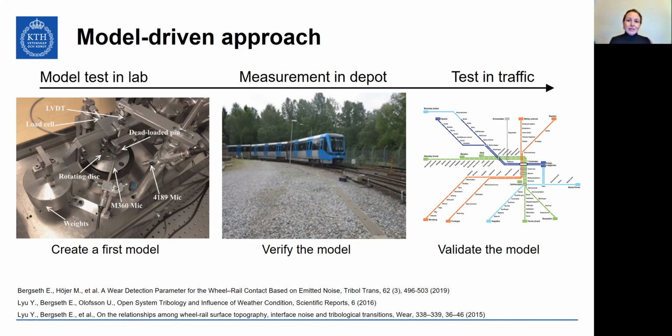And in this case, we could see that sound pressure amplitudes and sound pressure levels changed synchronously with the transition from normal wear to severe wear. And so we set some criteria according to this. And then we verified this model in a full-scale test in a depot and tuned this model.